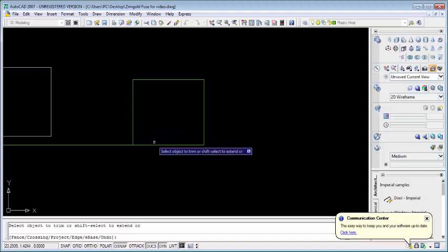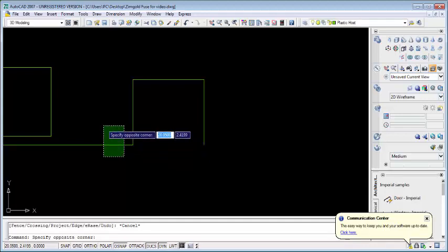If I tap this one, this side will go off, leaving this side for me. See what I mean? See, it's gone. This side is left, but this is not the side I wanted. I actually wanted to remove this one and keep this one, but in this case we've already removed this. There is no cutting this anymore, it will just be there. So use escape button to exit the command, then just select it and hit the delete key to remove it.